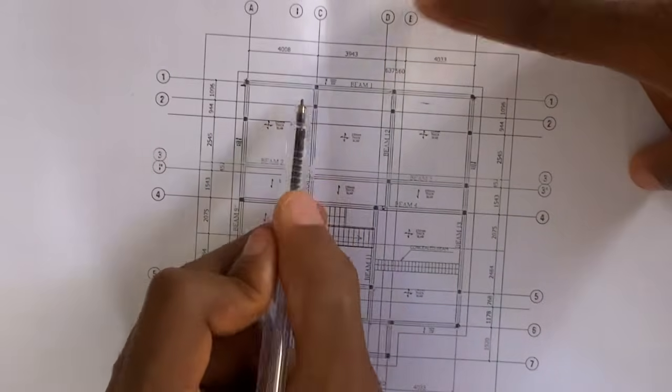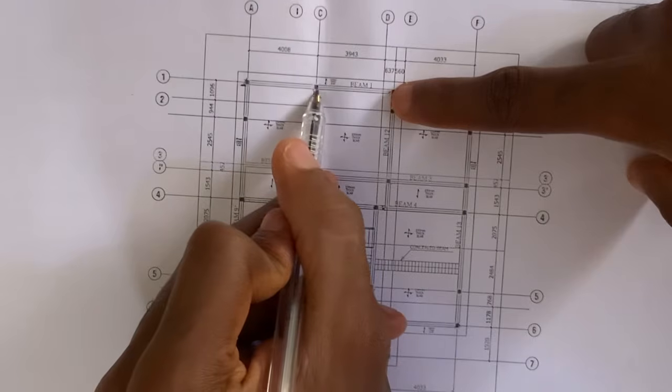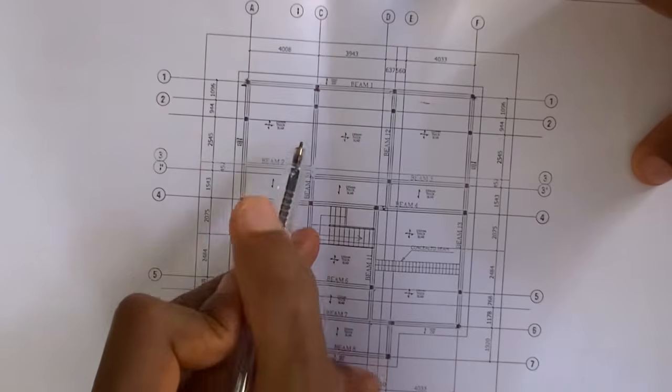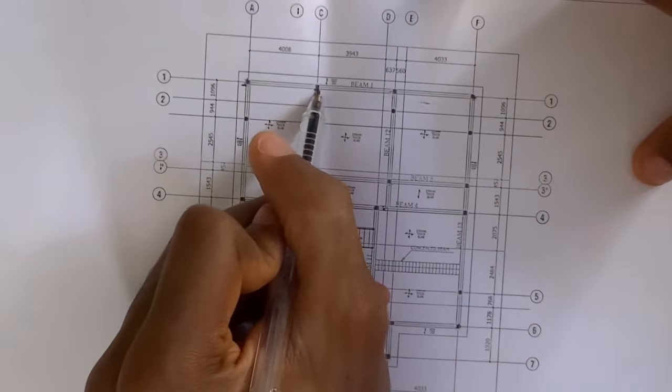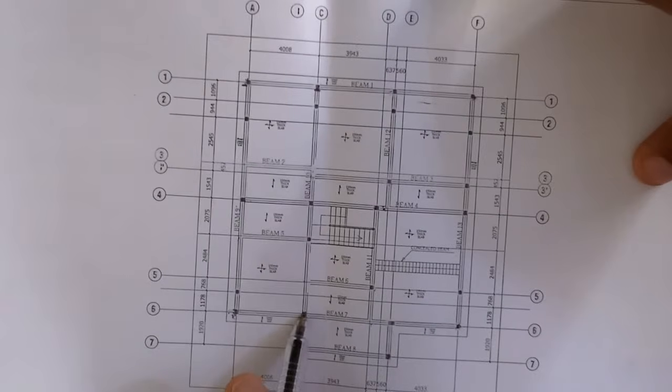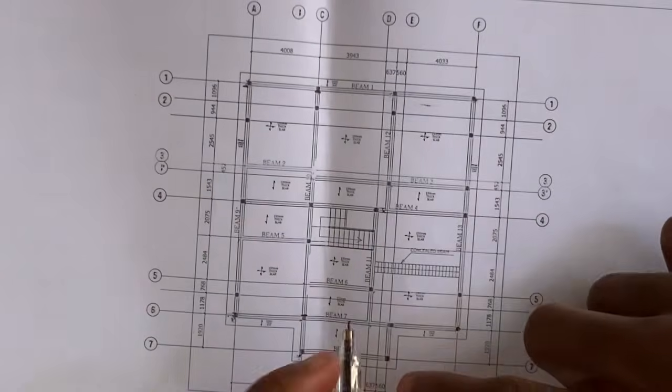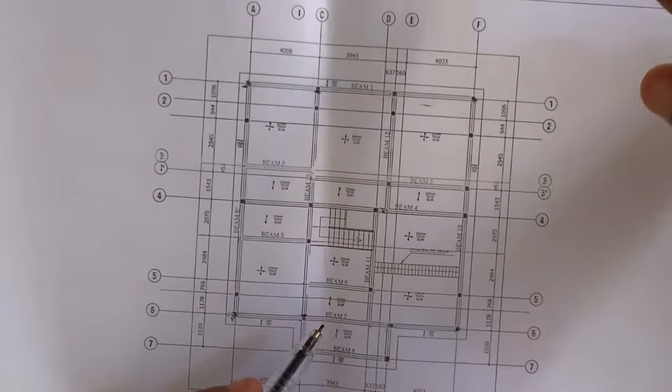Since we've measured for beam 1 separately, we can now start. Remember, I told you that the verticals will be what? In to in. So we can now measure for this beam 10 to be in to in, from this inside down to this inside, because this point here we've already measured as beam 7. We are not going to be measuring this thickness again 2 times. That's why we're cutting it from this inside down to this what? Inside, in to in. We are going to be calling that beam 10A.